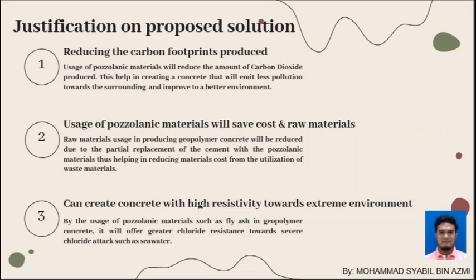Third one is it also can create concrete with high resistivity toward extreme environment. By using geopolymer concrete, the concrete will have a better resistance toward extreme environment. Geopolymer concrete that use pozzolanic materials such as fly ash will offer better chloride resistance rather than conventional concrete, which will be useful on an environment with severe chloride attack such as seawater. Implementing geopolymer concrete structure at extreme environment will have greater lifespan than conventional concrete.